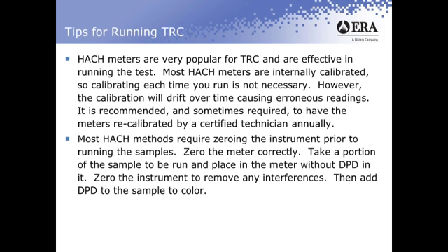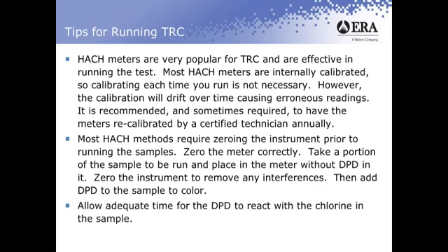Another important thing is to make sure that you allow adequate time for the DPD to react with the chlorine in the sample. Historically, Hach recommends in a lot of their methods that you allow somewhere between 2 to 3 minutes for the reaction to come to completion. Here's a tip I would recommend: unless you are in a hurry, wait that 2 or 3 minute period, put the sample into the meter and get a reading. I would then wait an additional minute and look at the reading again.